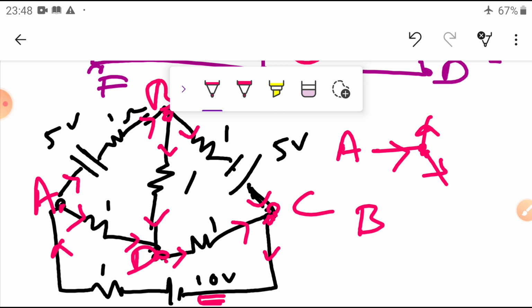In this case, you have to remember that one of the common nodes is taken as a reference, or you can say the datum node. So by making one node a reference, the remaining nodes decrease in size, then we are going to calculate easily. I think this problem is somewhat complicated. First we will do the simple problem. After that we will come to here. So this concept is the same thing. Before going to this complex network, we are going to do the simple problem for understanding purpose. After that we are going to do this one.